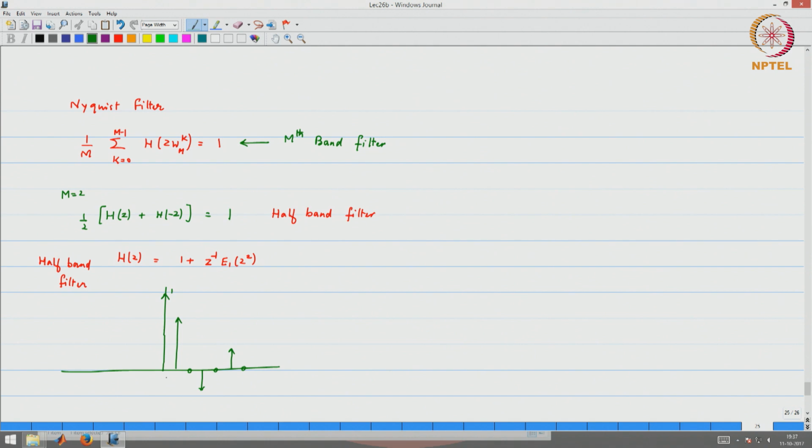Now, if I do the polyphase decomposition on both sides, this is a symmetric filter. Notice that you will get one coefficient of 1 and then all zeros elsewhere. So, this would be the repeating structure. So, this actually validates this particular form. Okay. So, the zeroth order polyphase component is equal to 0.